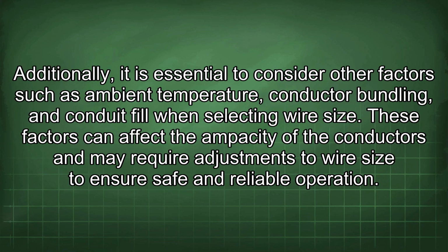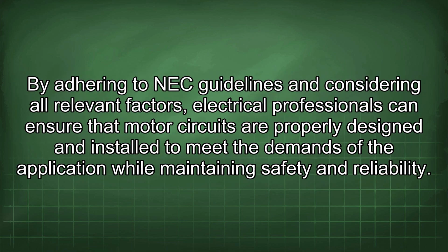Additionally, it is essential to consider other factors such as ambient temperature, conductor bundling, and conduit fill when selecting wire size. These factors can affect the ampacity of the conductors and may require adjustments to wire size to ensure safe and reliable operation. By adhering to NEC guidelines and considering all relevant factors, electrical professionals can ensure that motor circuits are properly designed and installed to meet the demands of the application while maintaining safety and reliability.